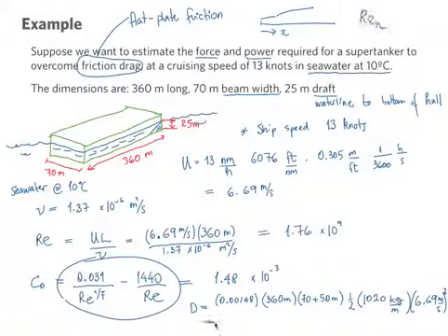And we can calculate that, and I get 1.46 meganewton. Pretty big number. Well, I'm using C of drag is equal to drag divided by 1/2 rho U squared A, and I've taken everything to the other side.